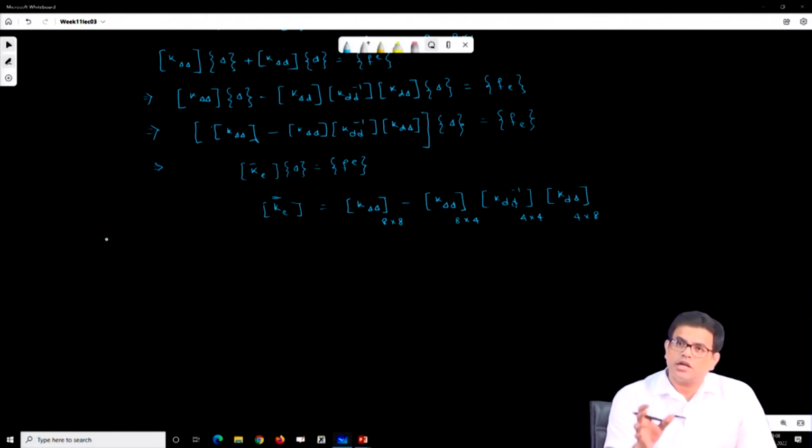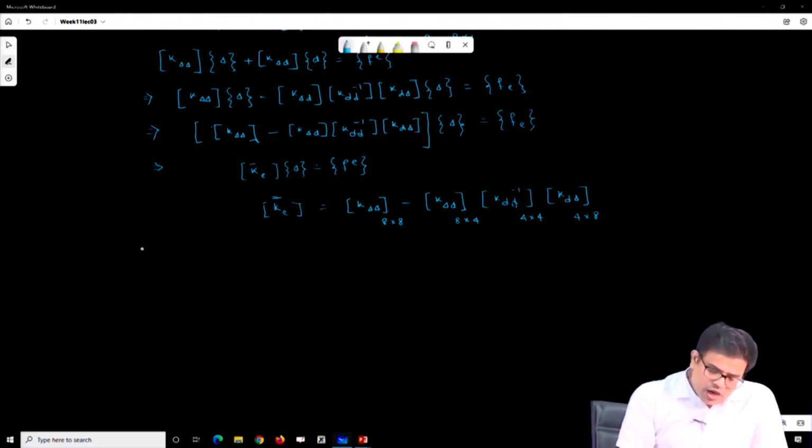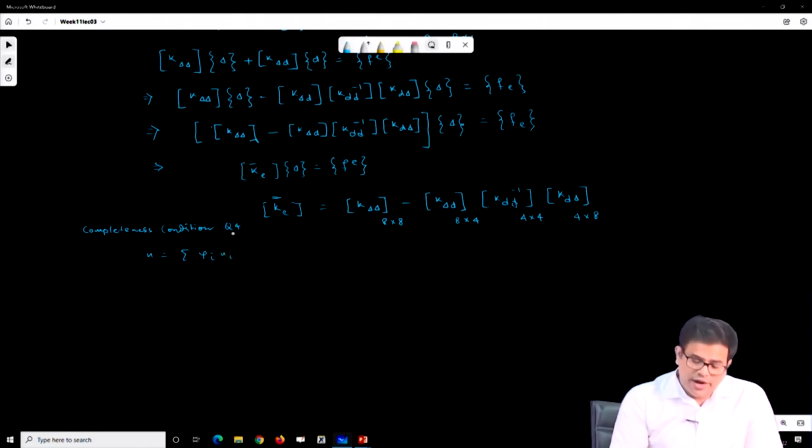If you remember the completeness condition of the Q4 element, suppose U is the summation of phi I times Ui, where Ui is the boundary variable.